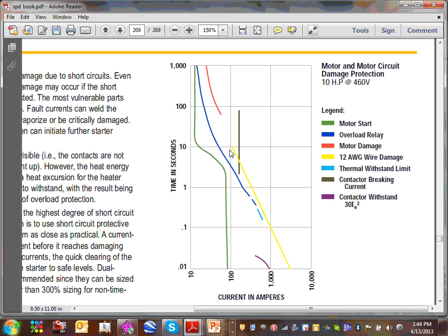I'm sure a lot of you guys know, equipment as well as conductors have 2 amp ratings. Amp rating is how much current they can carry continuously. That's the ampacity of the conductor. We all know that, right? Based on the temperature and the bundling. Number 2 is the withstand rating, meaning if you have a short circuit in this conductor, would this conductor be able to withstand the short circuit or the ground fault long enough for the fuse or the circuit breaker to open the circuit and de-energize it? Or would it turn into little pieces like we saw? That's called the damage curve of the conductor.